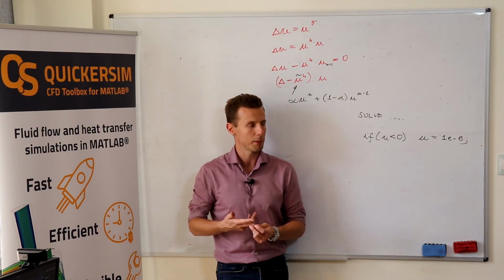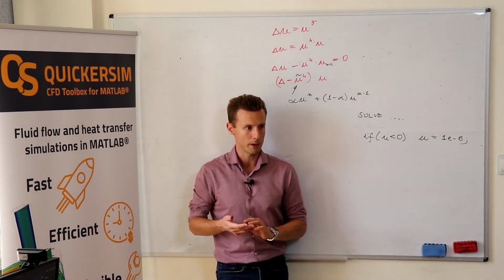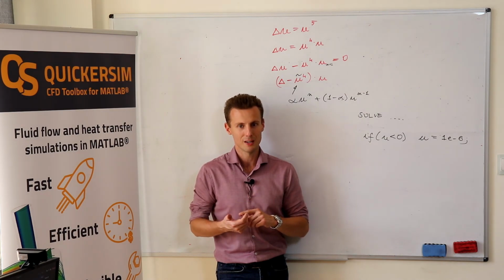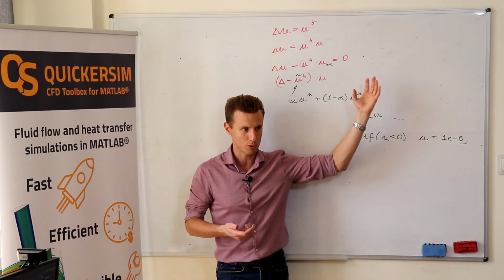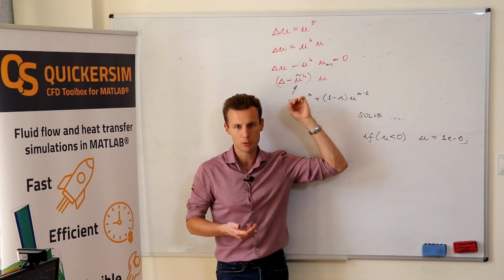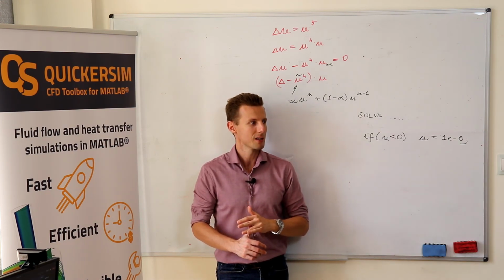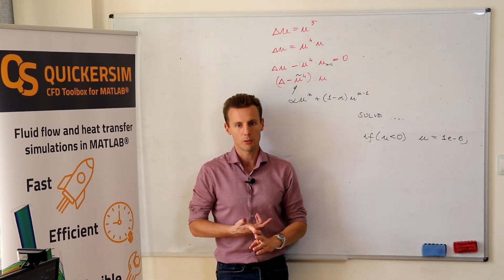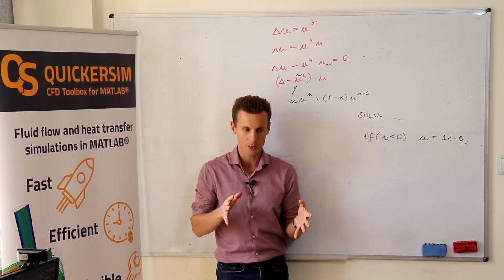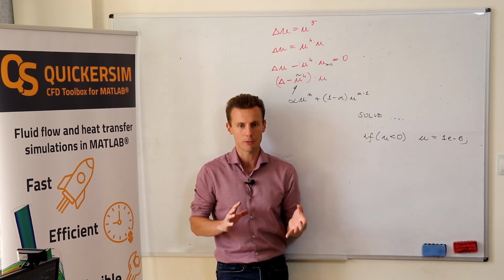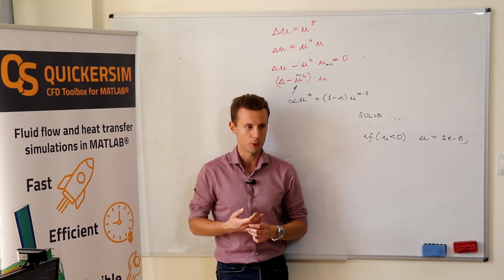If you're dealing with chemical reactions, evaporation, and source terms coming from such phenomena, use linearization, make the scheme implicit, which means take the source terms to the left-hand side, put them into the matrix, linearize, under-relax, maybe replace by a Newton-Raphson method if you know that you're within the convergence radius and you want to rapidly accelerate the convergence.